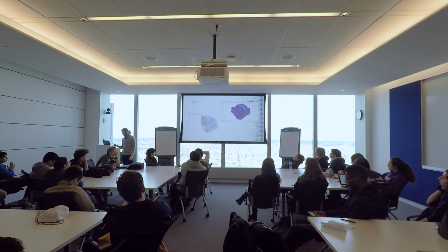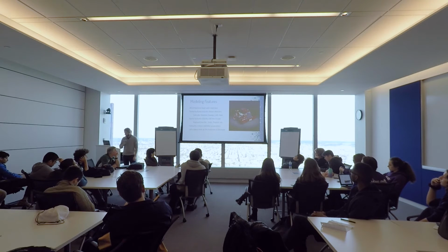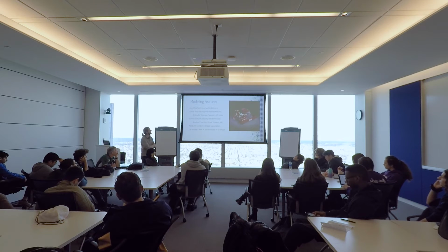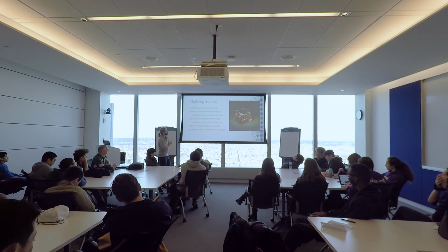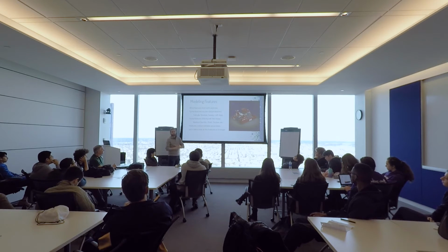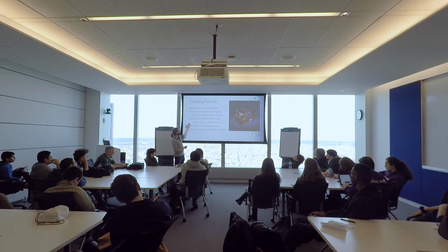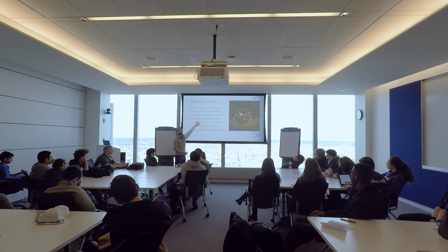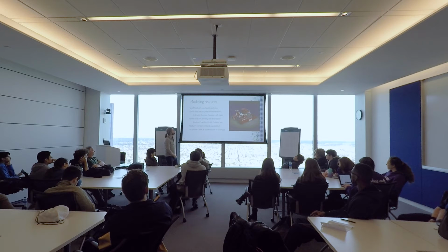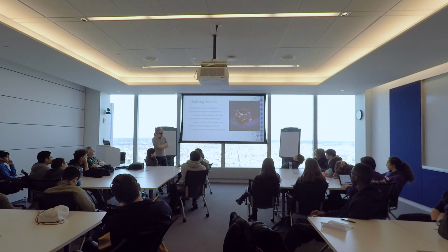We're gonna go into parts. So let's talk about features for a minute. Most features start with sketches. Almost all features start with sketches. Some require closed sketches, so an enclosed 2D sketch. And some directly edit the model, such as radius, chamfer, draft, and thicken. The primary ones that are used though are these guys here. Extrude and revolve are probably number 1 and number 2, especially in FRC. There are some sweep and loft applications, but mostly extrude and revolve.